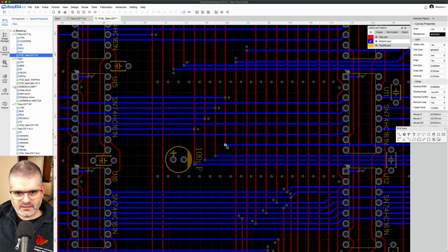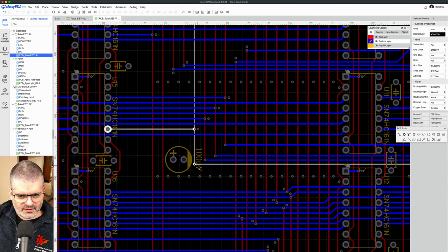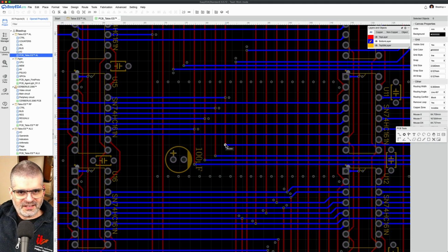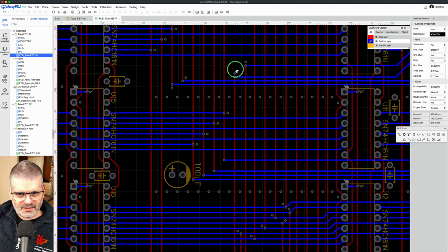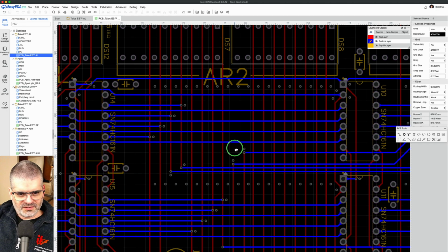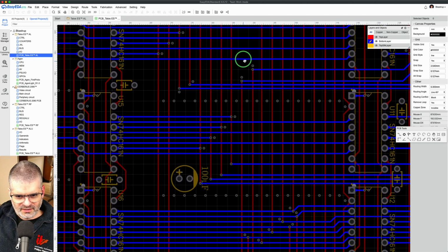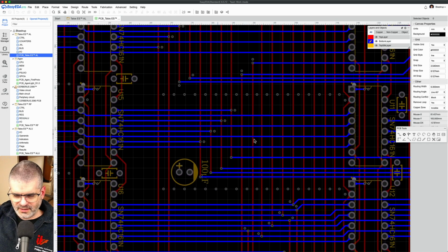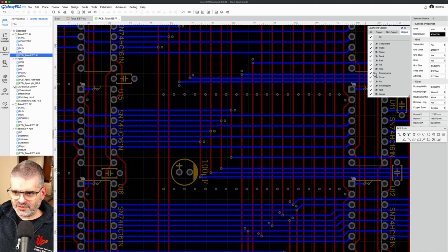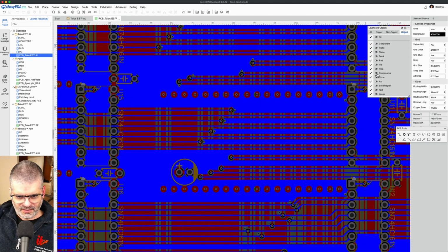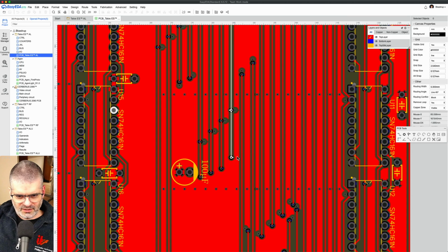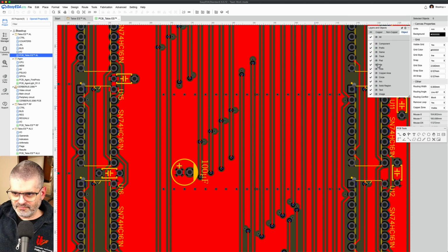Here I didn't, and I just noticed it now. I completely forgot return path vias here. What a bloody blunder. But I'm not going to make this again. The board works. Oh, what a pity. I probably didn't see it because I had the copper areas on, and it's difficult to see through all the copper. So I probably didn't notice for that reason.